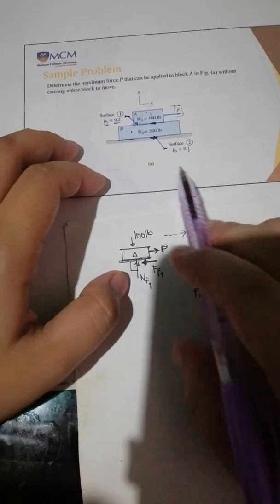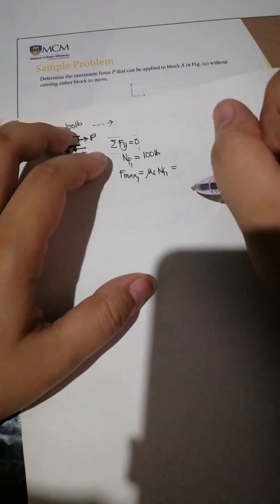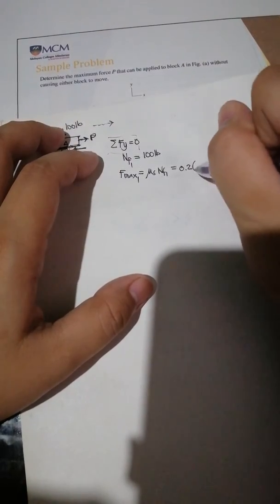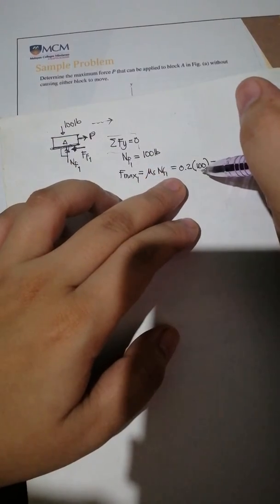Now that makes maximum static friction mu s times NF1, so we have F max 1. Our mu s on surface 1 is 0.2, as given in the problem, 0.2 times 100. That will be 20